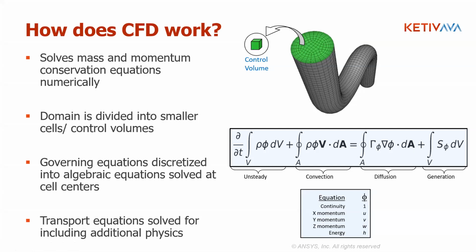So then how does the solver solve it? It uses algebraic equations that are derived from these partial differential equations to discretize the domain and then get a numerical solution for your CFD. The numerical solution is not the exact solution. It differs from the analytical solution because there is some error in it, but that error is so minimal that for all intents and purposes, CFD should give you pretty accurate solutions when you are trying to simulate fluid flow, either internally or externally in the domain.